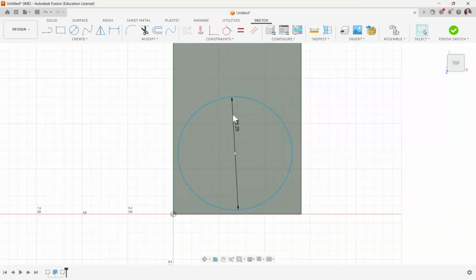Okay. But I'm not finished, because will the machine know to make a toolpath to just cut this out? No, it doesn't. It doesn't read your mind. It doesn't know that you want to cut this out. So you have to make a shape that you can tell it later in the manufacturing step, I want you to make a toolpath out of this.